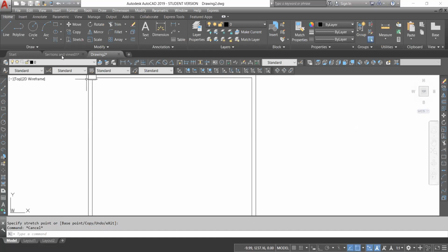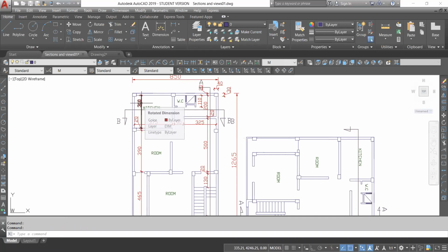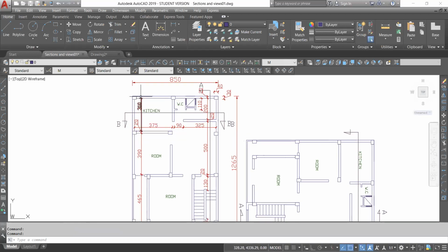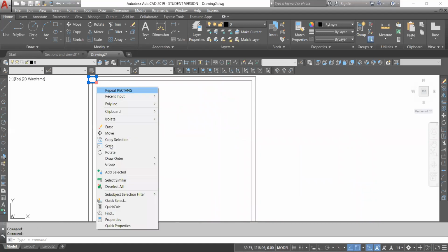So the next column here, I can draw it. It is also 30 by 40. It has a distance from this column, from this point to this point, of 310. But 310 till this point, I can increase it by 20 centimeters. It is 330 from this point to this point. So I can come here and click on this rectangle, copy.